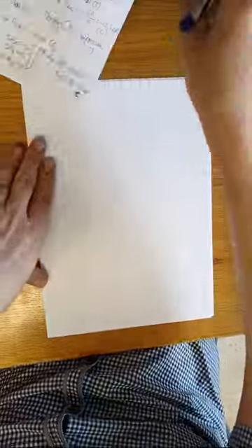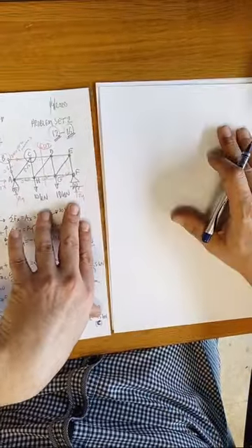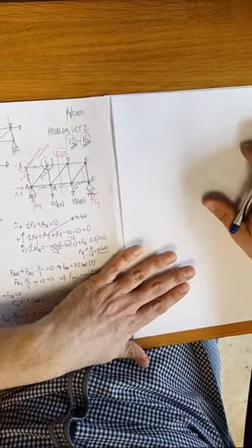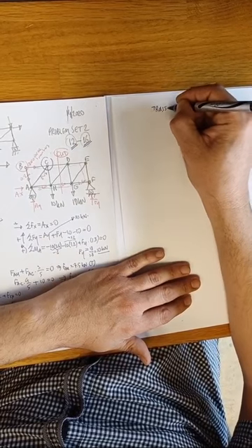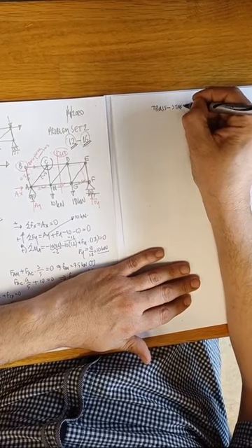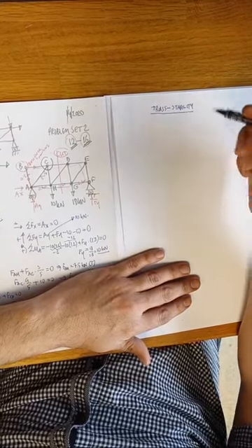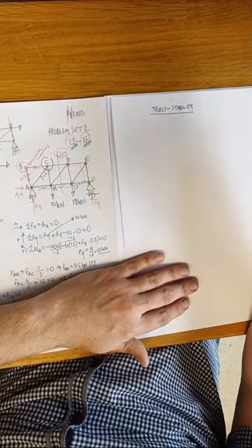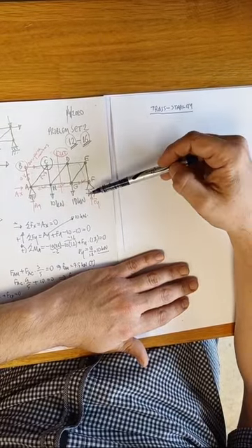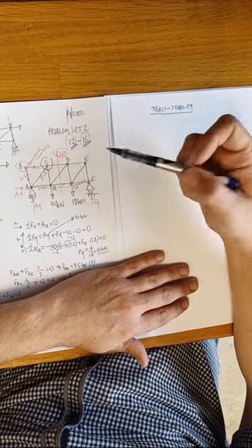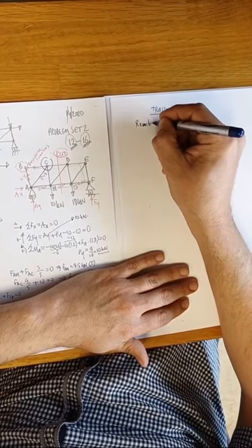What is the truss stability? I would like to also talk about the truss stability easily here by looking at this figure again, and let's also apply what should be the minimum requirement of the stability of a truss. So to do this, you have to check the number of the unknowns on the body. What are the reactions, for example? First, for our problem, reactions.